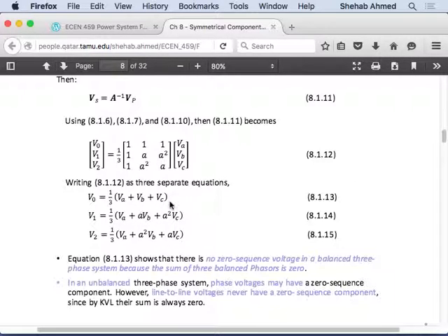So you would measure your phase quantities and calculate your corresponding sequence quantities and then come up with intuitions based on that. Yes? So positive sequence is always balanced. Positive sequence is balanced. Negative sequence is balanced. Zero sequence, equal in magnitude. So they're all balanced. But the positive and negative are also 120 degrees apart. The zero sequence components are equal in magnitude and phase. But the positive and negative sequences are balanced. So when we come up with a positive sequence circuit, we know how to solve balanced circuits. It's similar to what we've done before.